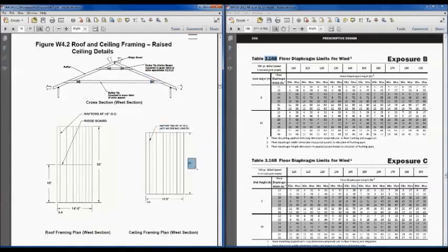So now we've got 21-foot rafter ties. Now we don't have a roof, we don't have a floor load on that anymore. So we'll see how we size those in just a second. But our rafters are going to be still 16-foot spans based on the horizontal projection. But again, because we've got some additional moment here on those rafters because of this tie, you're going to see that changes the design for these roof rafters here.